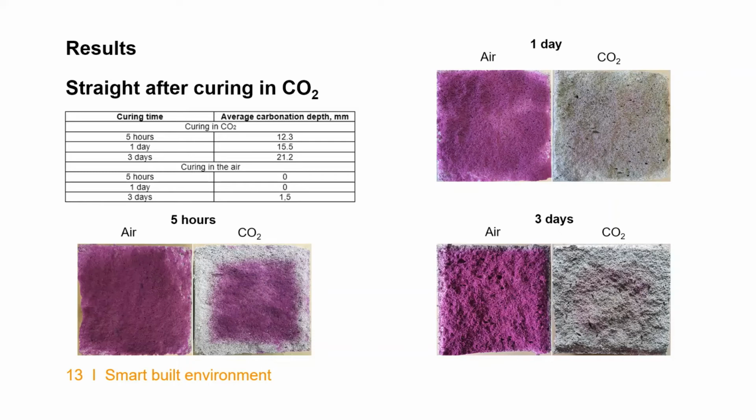After 1 day, the carbonation depth was 15 millimeters, but the carbonation degree was bigger. We can see that there is no solid purple color on that sample, but we cannot assess carbonation degree just using phenolphthalein. After 3 days, the carbonation depth was 21 millimeters, and in the air, it started to carbonate, at 1.5 millimeters.